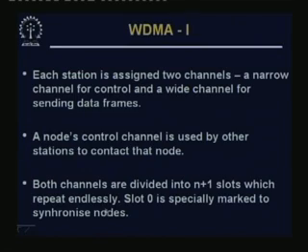So, in each channel there are n plus 1 slots, and a number of nodes, let us say 3 nodes B, C and D, can communicate with A at the same time, because for communicating to A, of course, they have to send in the channel or the wavelength which has been assigned to A. But how can all three send at the same time? Well, if there are slots in that channel and if they have booked separate slots, their data can go in different slots. So, B, C and D can simultaneously communicate with A.